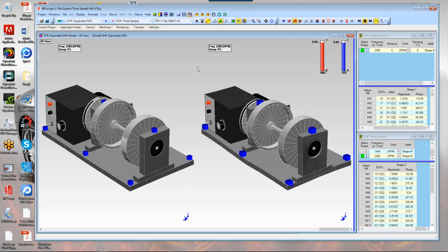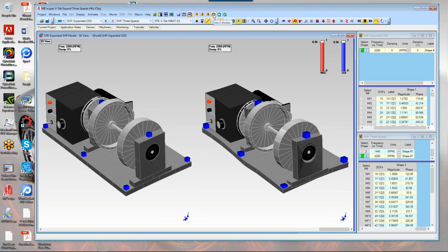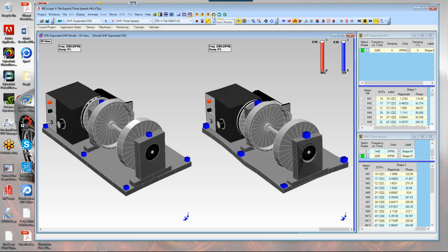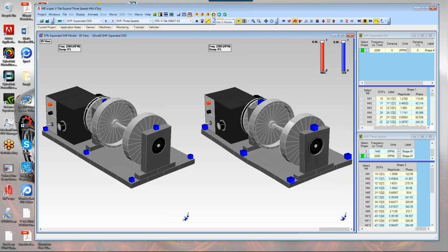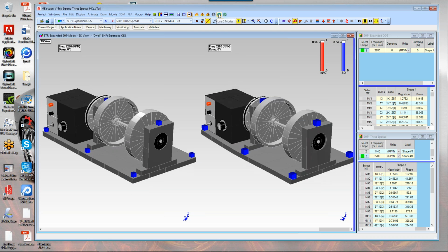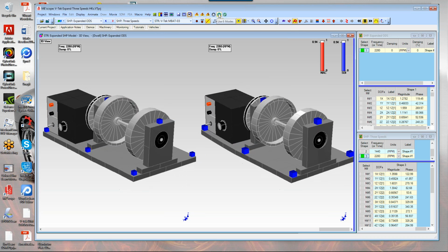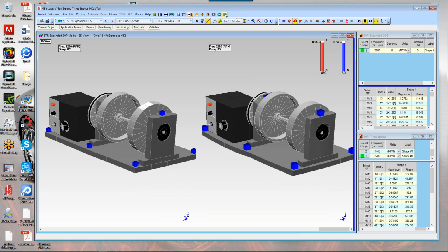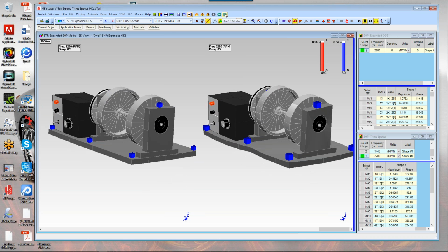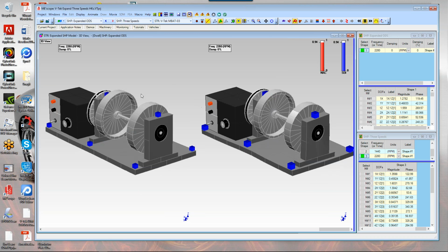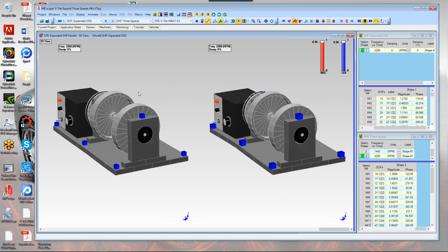So now these other three keys here allow me to simply select two of the modes of the modal model, which would be two of the rigid body modes, six of the rigid body modes, and we saw the modal model actually had some flex in it for modes 5 and 6, or all 10 of the first modes, which would be essentially 6 rigid body modes and 4 flexible modes, curve fitting all those mode shapes to the experimental data. This is what we call shape expansion in MEscope, and that's one of the commands in a shape table.